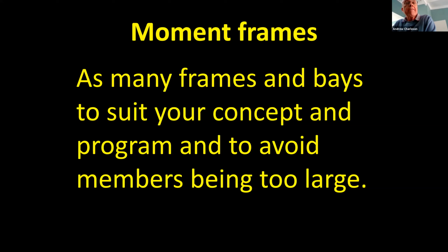You won't have very few frames, because that would mean that your structural members would be too large, and that would probably be inappropriate for your designs. So you have to create a balance between the numbers of frames and bays and the sizes of the members. You know, the more frames and bays, the smaller the members. But you're able to make that choice for your concept and program.